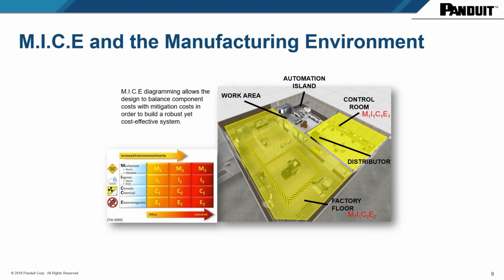As you go down to the floor level of a given work area, you will start seeing more restrictions. So at the ceiling level, you could still be at a control room rated environment. The only thing we need to worry about in that space is some emitted radiation. So there could be some power systems running in the ceiling and conduit and other places that can affect communication. So therefore, cabling in those spaces has to be also considered to look for where we have emitted radiations.